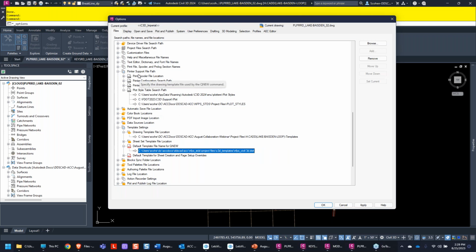You just quote unquote make a project, okay, and then you start adding folders and you add in your AutoCAD resources. The one thing I would recommend is to make sure that you are checking those files. A lot of people don't realize that in their standard files, they have references or other things, like a template may reference your logo. It may reference a border. Some people reference their border and then they put in their title block just the actual text and so on, or an attribute, or a title block, right?